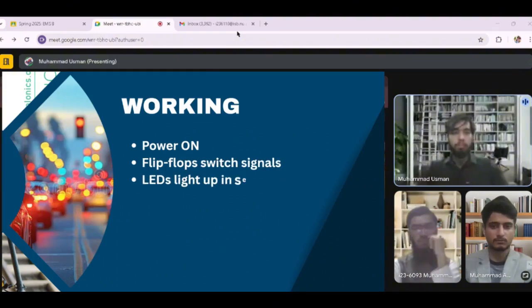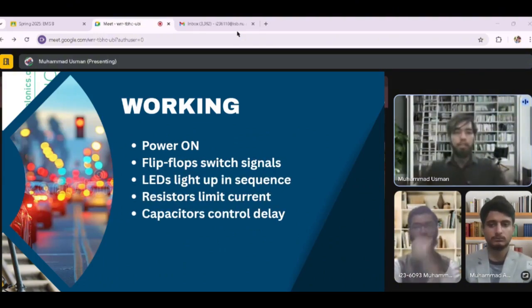Here's a breakdown of how the system works. The first 555 timer operates as an oscillator, continuously sending pulses to the second timer. The second timer IC then interprets these pulses and switches the output between three states, which controls the LEDs. The timing intervals are controlled by the RC resistor capacitor network connected to the 555 timer. The voltage across the capacitor causes the timer to trigger a reset, creating the on and off state for each LED. Essentially, we are using timing logic to simulate a state machine where each light phase represents one state.